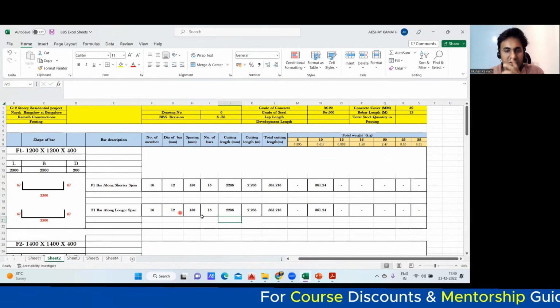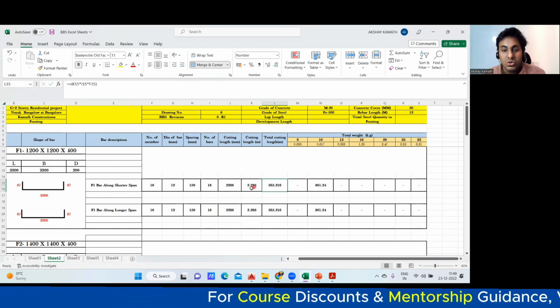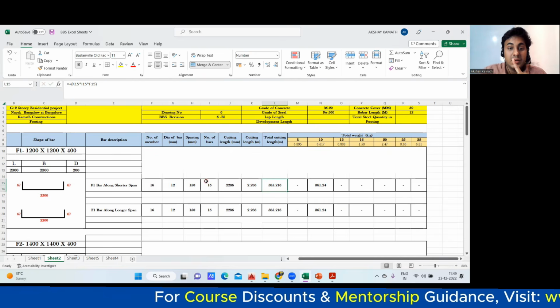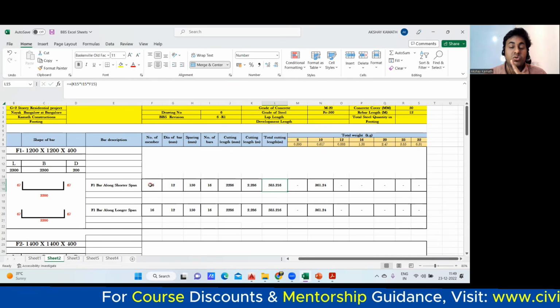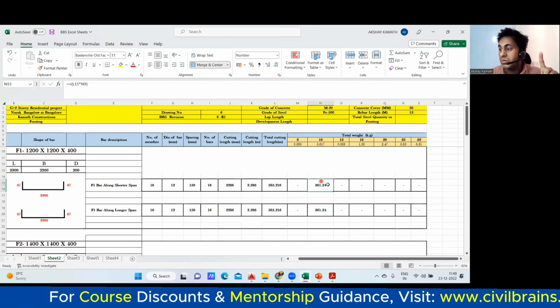Done. Okay, fine. And total cutting length will be how much? 2,286 is the cutting length of one bar. Multiply by the number of bars. Number of bars I'm getting, 16 into 16 I have to do because there are 16 F1 footings. Okay, got it? So totally it will be how much?